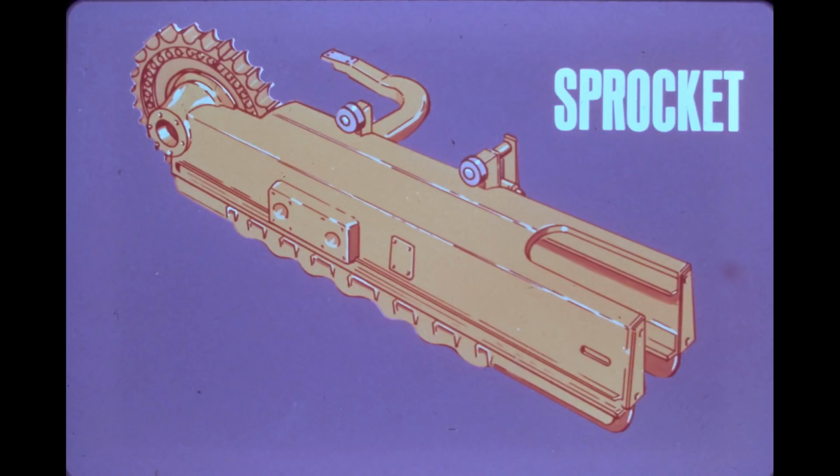For example, if 4 consecutive sprocket teeth were numbered 1 through 4, teeth 1 and 3 would make contact on the first revolution of the sprocket, 2 and 4 would ride free. On the second revolution, 2 and 4 would make contact, and 1 and 3 would ride free. The hunting tooth feature is accomplished by chain design and by using an uneven number of teeth on the sprocket. Hunting tooth design increases sprocket life.